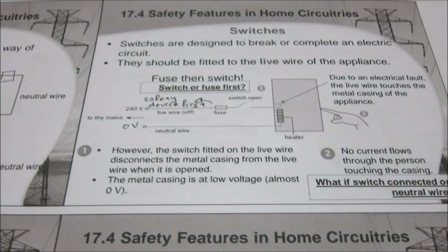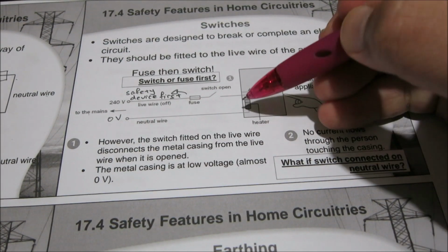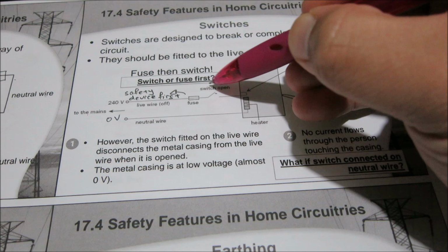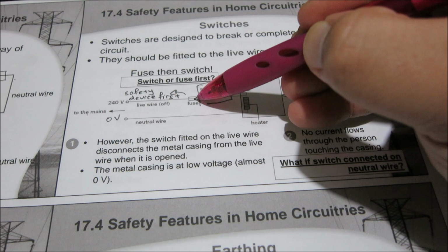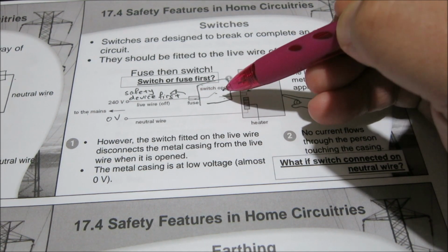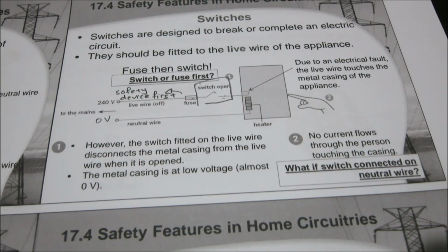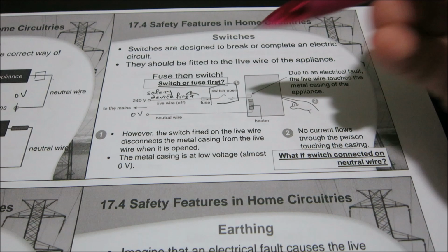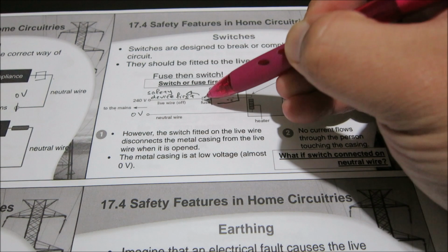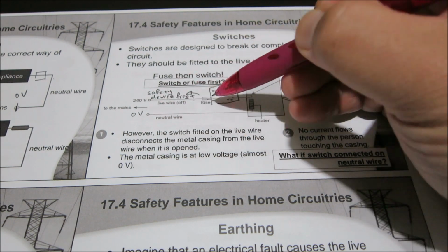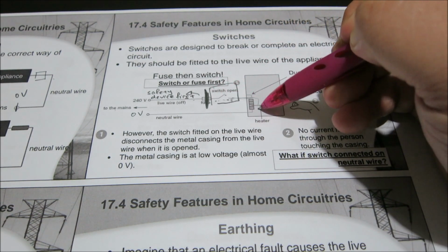Now, when we talk about fuses, we talk about switches. So switches basically is an electrical component that breaks open your circuit so that current will stop flowing. Now, you place your fuse before your switch in all situations because you want the fuse, the safety device, to break before anything that you can touch. So the switch is something that I can touch. It's something that you have to touch to switch on your appliance. So you want the safety device first, so in case of any fault, it is broken here. So anywhere you touch after here is all safe to be touched.